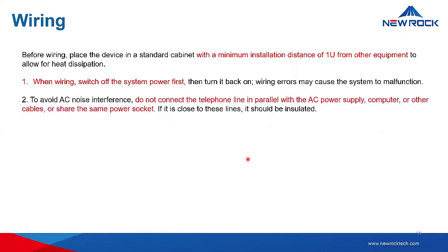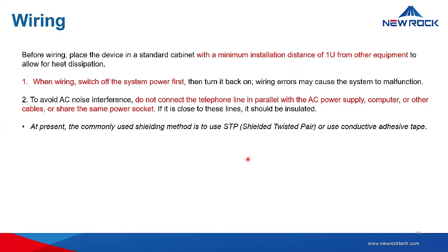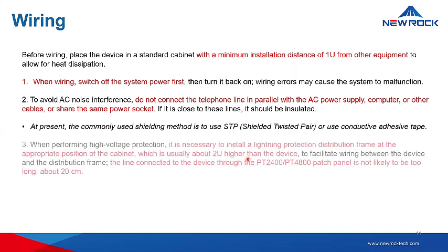Then, you need to avoid AC noise interference. Do not connect the telephone line in parallel with the AC power supply, the computer supply, or any other cables, and do not share the same power socket. If it is very close to these lines, it should be insulated. We can use STP, the shielded twisted pair, or use a conductive adhesive tape.